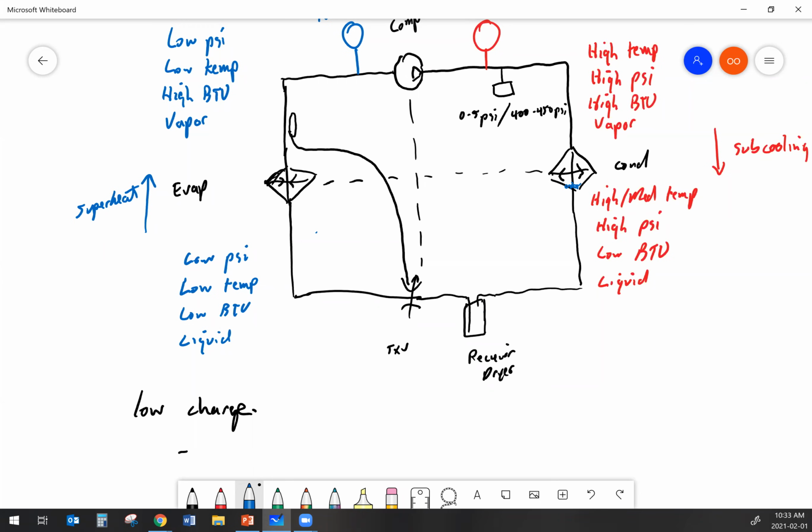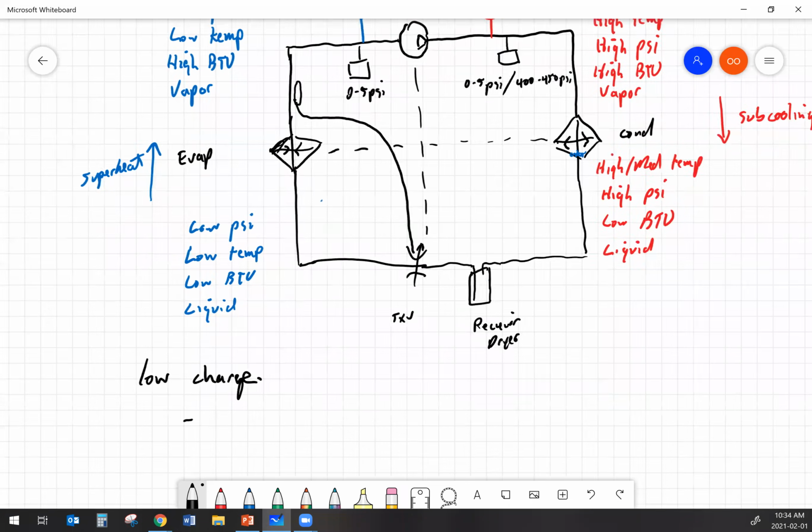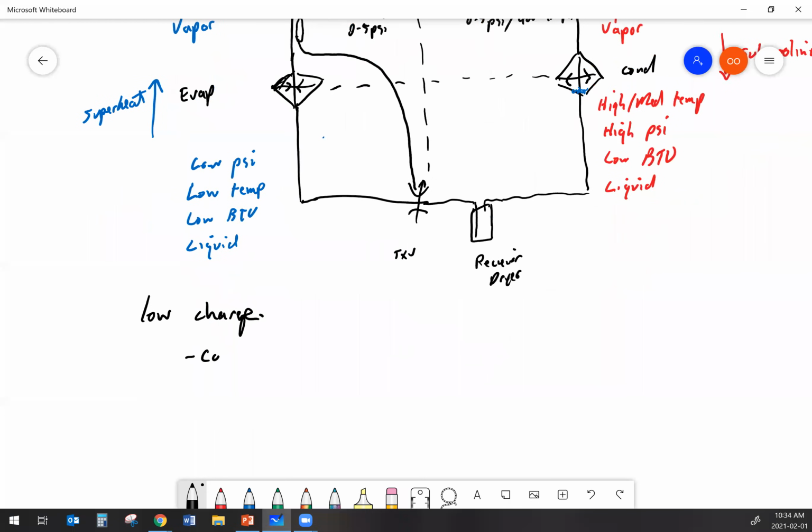And secondly, when the compressor is pulling down the pressure, if it has what a lot of systems nowadays are supposed to have, or starting to have, I should say, if it has the low side switch on this side and not built into the high side switch, if it has a separate low side switch, what will happen is that low side switch, it'll cut the compressor off as that pressure drops down. So you're going to end up with constant compressor cycling.